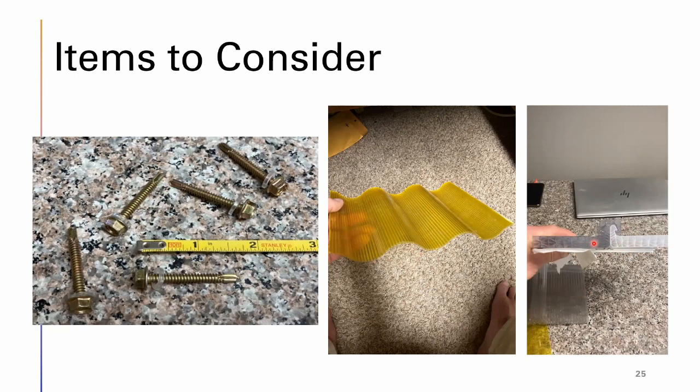When you're designing your greenhouse, you have to consider your glazing, not just for heat retention, but also the transmissibility, the amount of energy that it can transmit. Olson's is in Salem, which is by Provo. They're the largest greenhouse in the state of Utah. I think size-wise they're about 3.1 million, but that includes their Santaquin site, Provo site, and they have a Colorado site. They use almost exclusively 2-layer 6 millimeter or 8 millimeter polycarbonate.